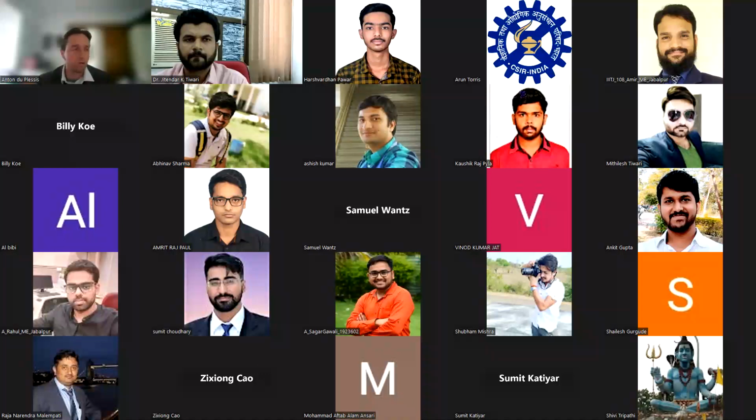Like the example I showed of the part with different scans that were needed. Progressively, more and more artifacts take place, which make it very difficult. So I would say there's not a hard restriction, but depending on the equipment you've got, if you want to analyze very, very dense steels of large size, you need a very high X-ray voltage, which is not typical for a desktop CT kind of instrument, for example.